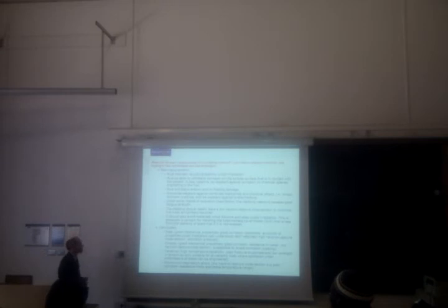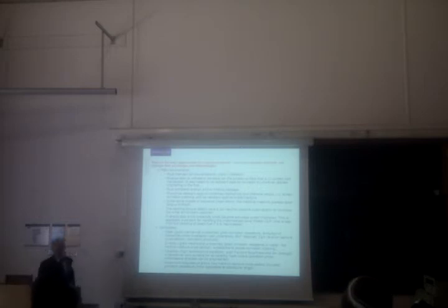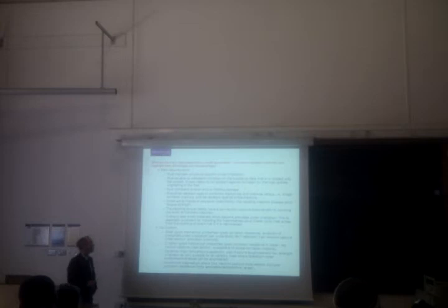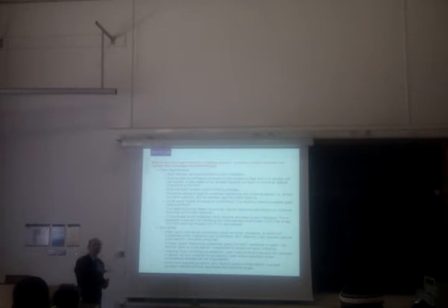So steels, remember, have very good mechanical properties. We like steels, we've been using them a long time, we understand a lot about their behaviour. They're very, very good at corrosion resistance, but they have a relatively high neutron capture cross-section. So we can use them, but if we're going to use them, then we have to use a correspondingly higher enrichment than we would otherwise have to use, and that costs money.